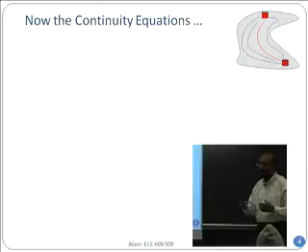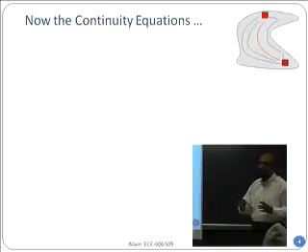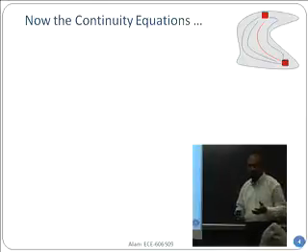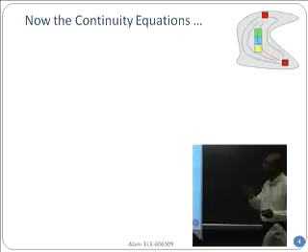I'm talking about more like 15 to 30 angstroms, a relatively big region, almost macroscopic in terms of properties. Effective mass and mobility are valid concepts, but the size is small compared to the device dimension. In that case, if you look at the green, blue and yellow boxes, you will see electrons streaming into, let's say, the blue box, and gradually streaming out of the box.